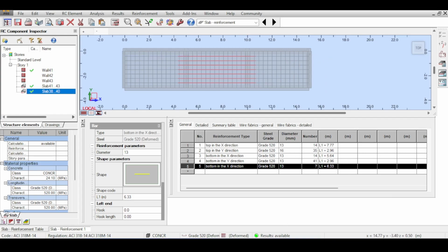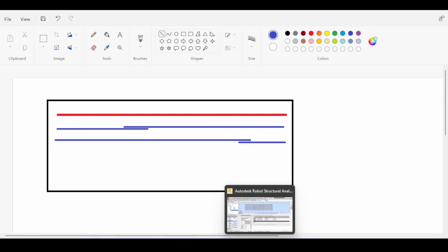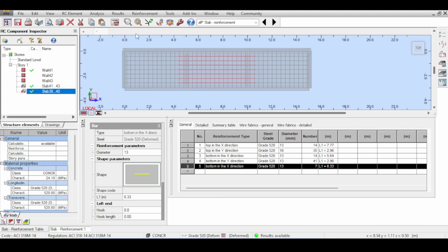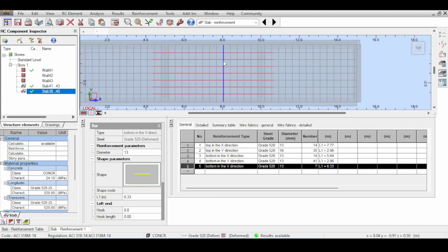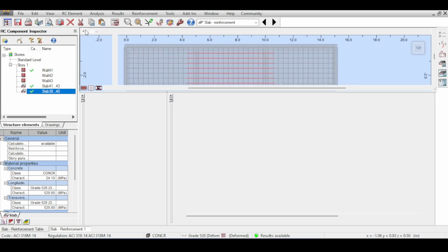Now, you would think that this is wasting money. You would think that you should break it like this. You should break it in 1 point because whenever you break a steel bar, you need to provide development length, which means you need to provide steel, which means cost. You would think you can break it in 1 piece like this, but you cannot, truth to be said. Why? This is the negative steel, this is the negative side, and this is the positive side.